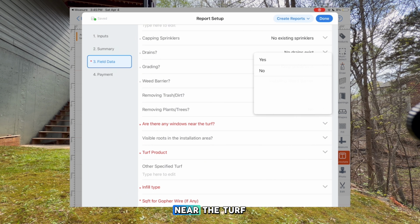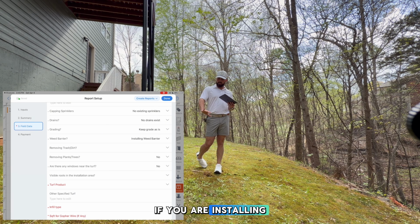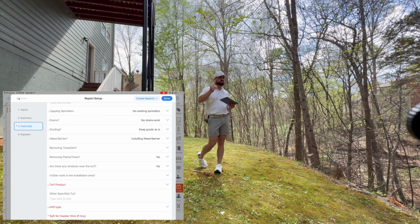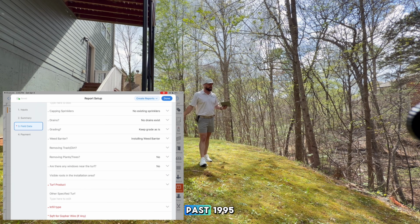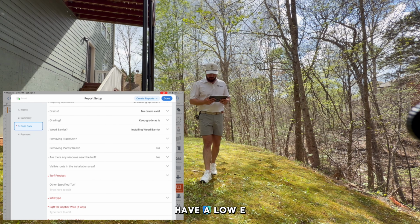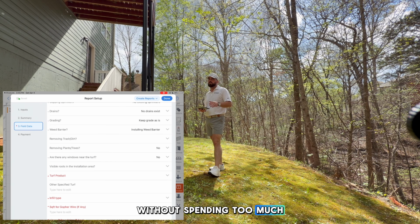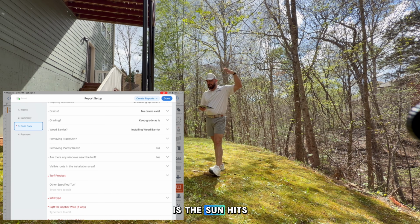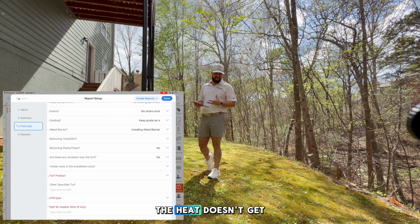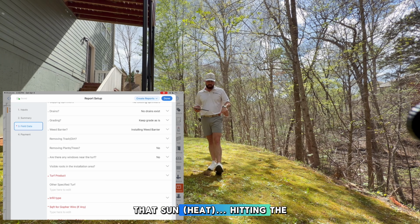Are there any windows near the turf? No. But that being said, if you are installing turf and there's a window above it, and say the window was installed, I don't know, anything past 1995, there's a good chance that it's going to have a low E coating on the glass. And the purpose of a low E coating, without spending too much time talking about it, is the sun hits the window, the low E coating reflects the sun, so the heat doesn't get in, better for energy efficiency. Where's that heat going? That sun hitting the turf.